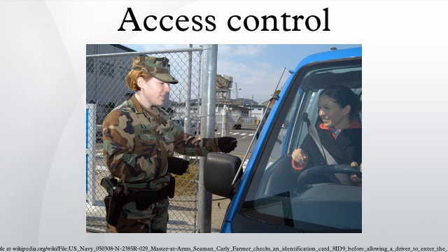Access control system components. An access control point, which can be a door, turnstile, parking gate, elevator, or other physical barrier, where granting access can be electronically controlled. Typically, the access point is a door. An electronic access control door can contain several elements. At its most basic, there is a standalone electric lock. The lock is unlocked by an operator with a switch.